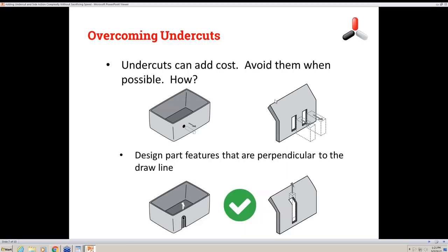We're going to pull those out. On the bottom here, we're going to look at a couple of different ways in which we can try to reduce them. This one right here, we have the same little hole down here on the feature, except what we did is push this wall back a little bit, and we open this up all the way to the thickness of that hole. And what that does is it allows, just like we looked at with the clip features,